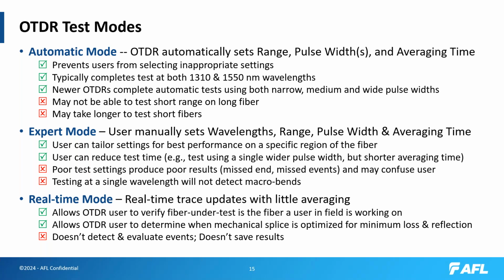Whereas in automatic mode and expert mode, when a test is complete, you can manually or automatically save the results, and analysis software would be run to identify and locate the splices, the connectors, the splitters, the macrobends, and save all of that in what's called an SOR file, from which you could generate the report or review the results or provide this SOR file to someone else to review.